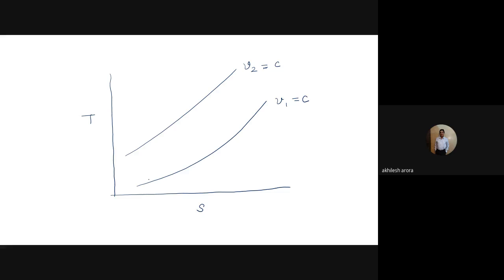If I choose this as the initial state point, point number 1 here, the first thing is that I am going to draw the constant volume cycle, or the Otto cycle. So the first process is reversible adiabatic compression, during which there is no heat transfer. So this is the process which is shown here.